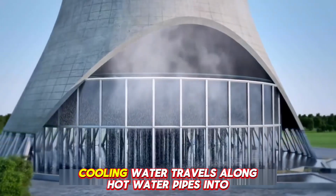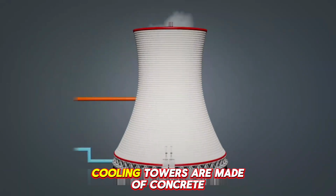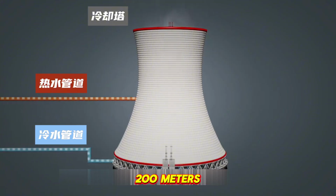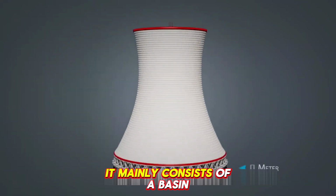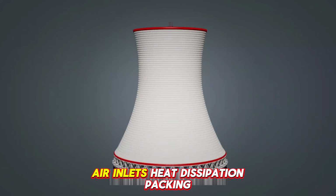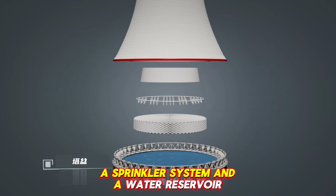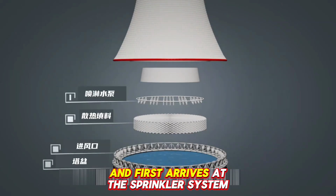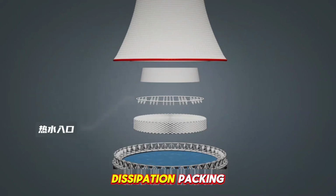First, the hot cooling water travels along hot water pipes into the cooling tower. Cooling towers are made of concrete and can typically reach heights of up to 200 meters. The inside of a cooling tower is not very complex. It mainly consists of a basin, air inlets, heat dissipation packing, a sprinkler system, and a water reservoir. The hot water passes through an inlet and first arrives at the sprinkler system. After that, the hot water reaches the heat dissipation packing.